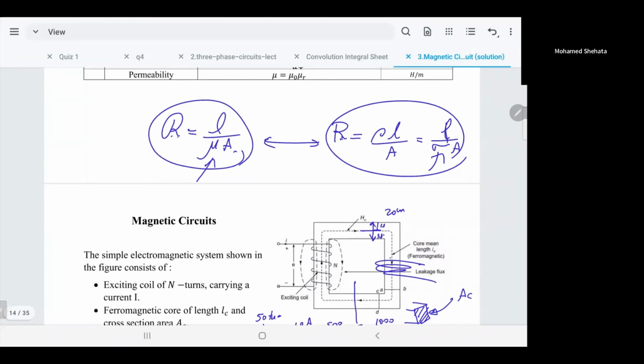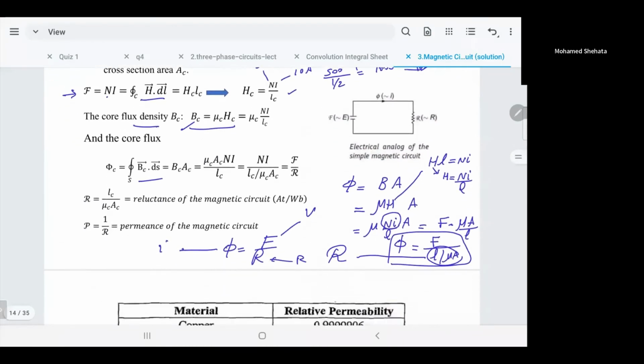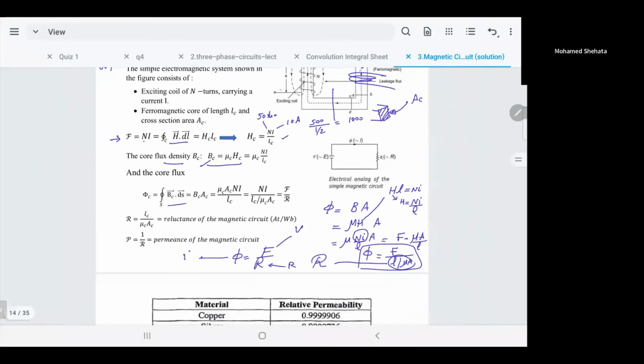Both are the same. So now, this magnetic circuit, we can make it simple. We say, okay, this magnetic force, the coil, I will represent as a voltage. I call it F, and it's equal to Ni. And the reluctance of this material, of the core, I will represent as a resistance, and it's called reluctance. And the magnetic field going through, that's called phi. I think it's time to make an example and see how we solve this.